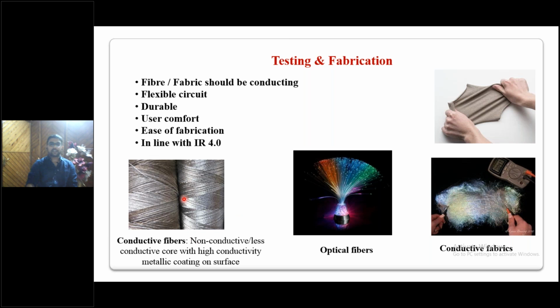These are conductive fibers, which have a non-conducting core and a coating of conductive material from the outside with high conductivity. This is conductive fibers. We can use optical fibers. This is a conductive fabric. If you stretch it, you will get a resistance. So based on your choice, you can apply all these things. Then you can connect all these conductive fibers with these conductive fabrics to make it fully flexible.